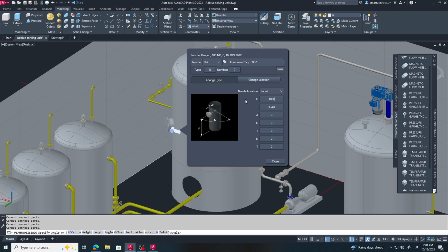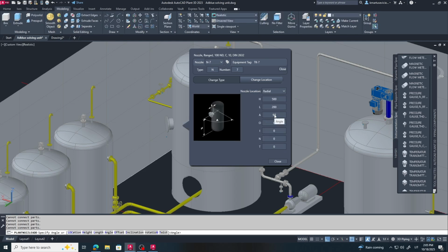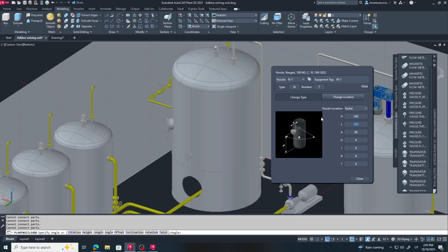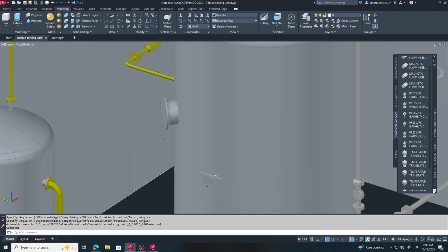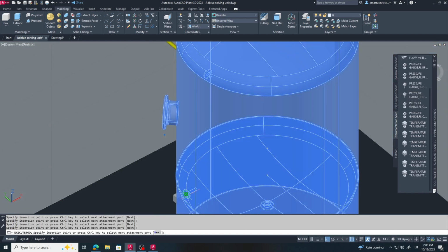I also add a temperature transmitter. It works together with the heating coil. When the transmitter detects that the water temperature drops below the set point, it sends a signal to turn the coil on. Once the temperature reaches the target value, the coil switches off. This keeps the water temperature stable automatically.